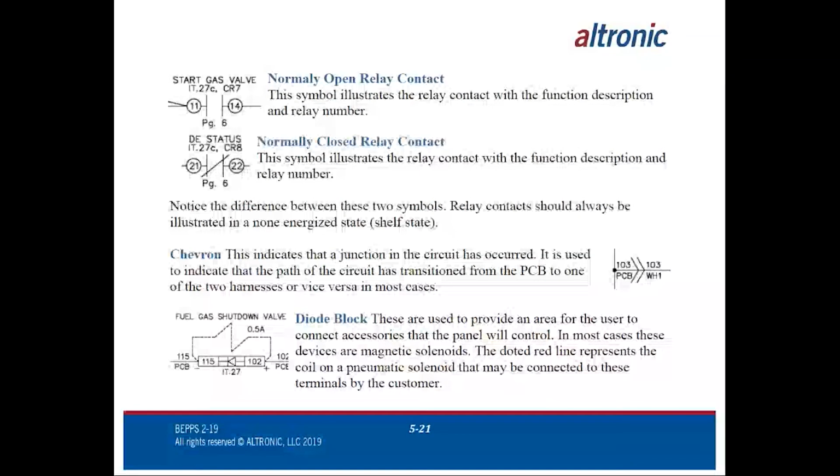So notice the difference between these two symbols. Relay contacts should always be illustrated in a non-energized shelf state. That is the general rule that we follow. I'm not going to say we get that perfect every time.